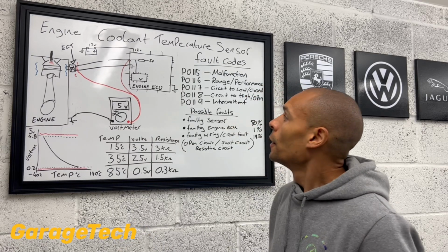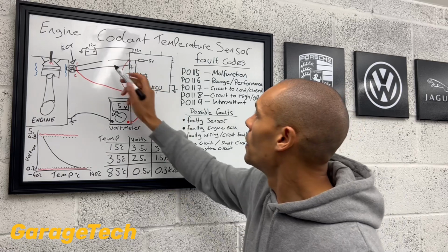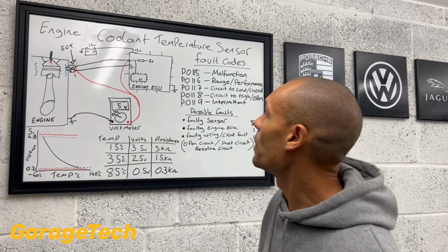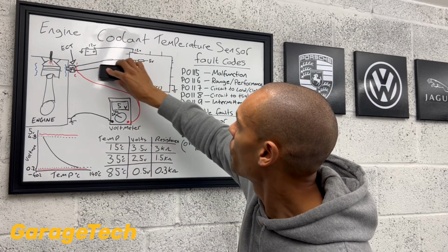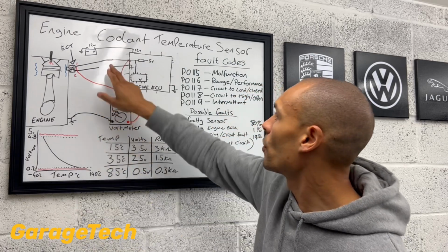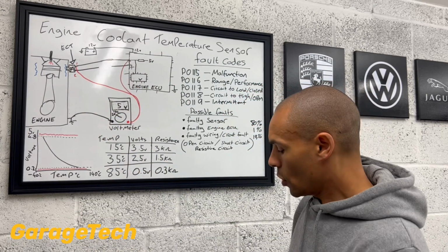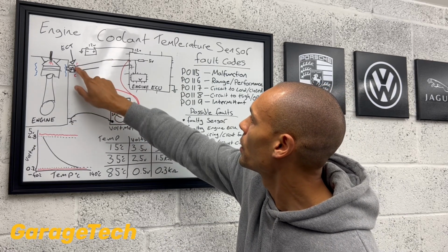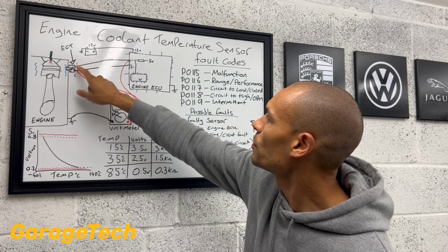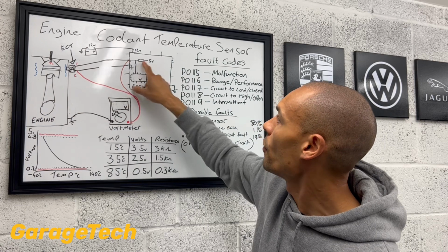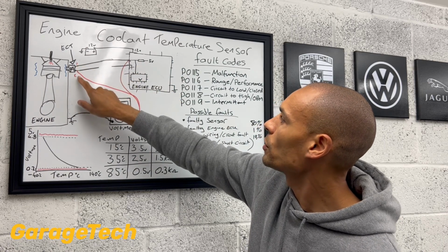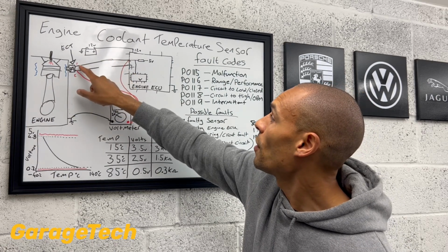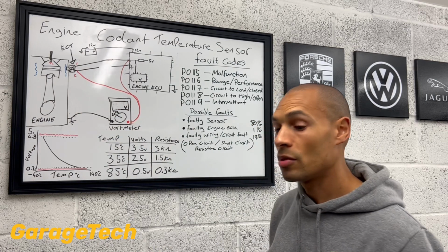Okay, right. Let's just think now if we had an open circuit on the earth. Okay, so let's say, for example, now we've got an open circuit on that earth wire. If we go and do our first check over here, we're not going to pin 1 anymore now, we're going to go to pin 2. If you went to pin 1, you're going to see the 5 volts because it's coming all the way down to there. In pin 2 you'll also get 5 volts. That's just going to indicate then if you're getting 5 volts on both of those pins at the temperature sensor.